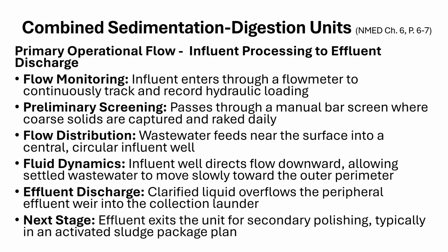Okay. So with these package plants that we've been talking about, influent to effluent: how do we process the influent and get to the discharge of the effluent? Well, first thing is the influent's going to enter through a flow meter, so we're going to track and record the hydraulic loading. Hydraulic loading, a term we've used before, is the volume flow rate coming into the plant. What's the daily flow, million gallons per day, coming into your plant? What are you treating? You are required to track that and record that.